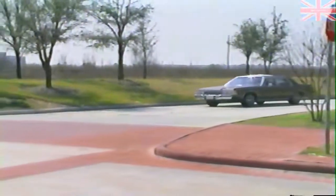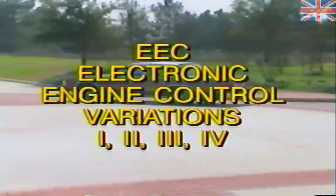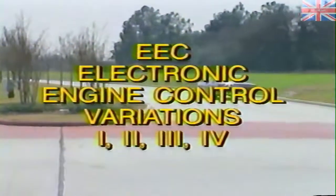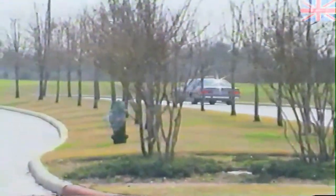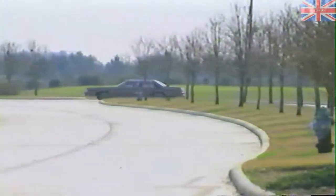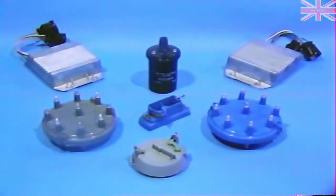Ford has utilized one basic overall system for electronic engine control. Most people refer to this as the EEC system, introduced by Ford in 1978. Over a period of time, there have been numerous versions. The EEC-1 system controlled ignition, timing, and the emission system. It was used on the 5-liter Lincoln Versailles. This system did not control the fuel system.